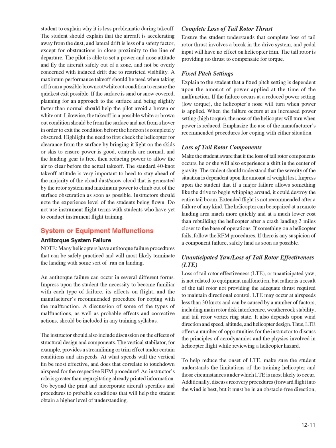Loss of tail rotor components. Make the student aware that if the loss of tail rotor components occurs, he or she will also experience a shift in the center of gravity. The student should understand that the severity of the situation is dependent upon the amount of weight lost. Impress upon the student that if a major failure allows something like the drive to begin whipping around, it could destroy the entire tail boom.